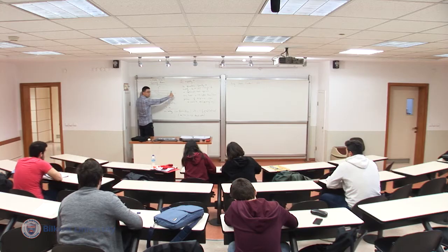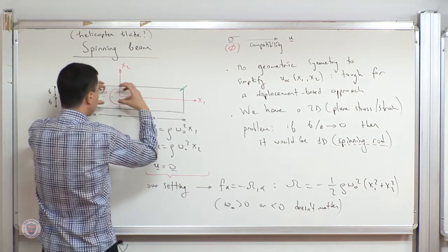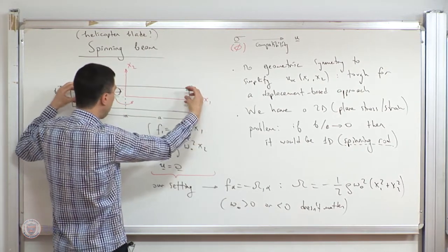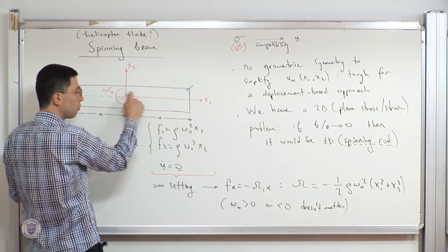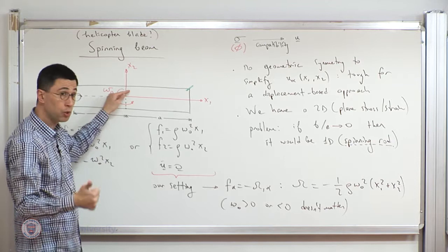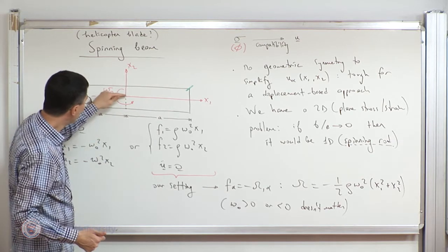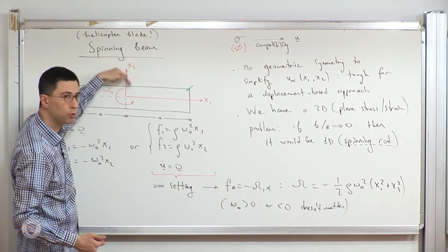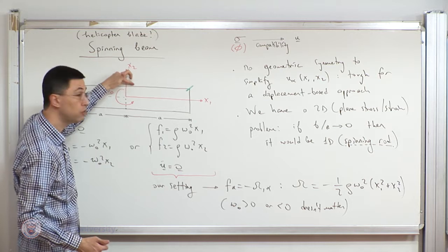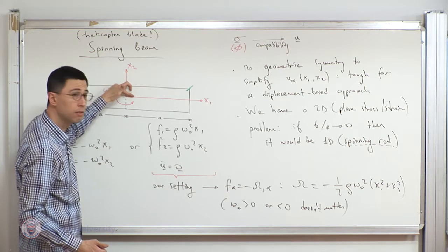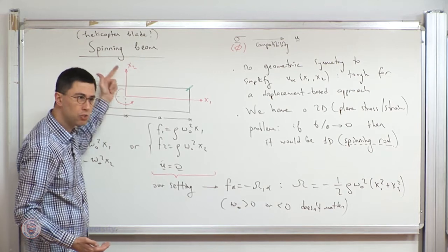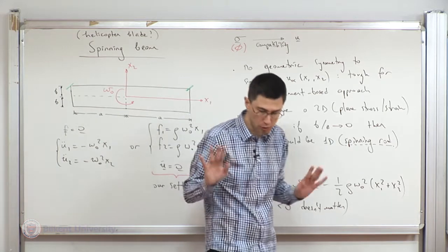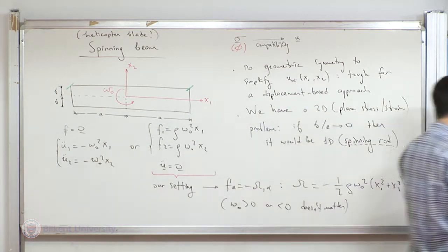I have a beam. It's rotating rapidly. So under the influence of those inertial forces, it will try to expand, right? And some stresses will occur throughout the structure. Now, stresses will certainly occur, right? And moreover, stresses at, for instance, sigma 2, on the plane with normal 2 in the direction 2, it's traction free. Here it's 0. And here, it's not 0. So that means the stress is going to vary, right? So stress is not a constant. That's an immediate observation we can make. It's a very simple observation, but it is immensely helpful.